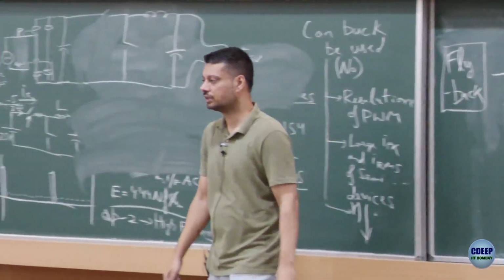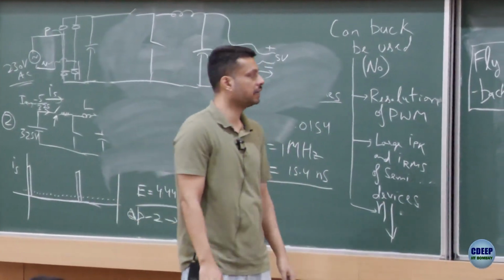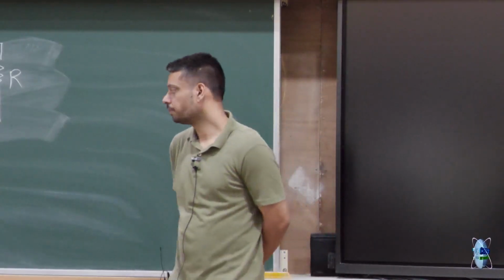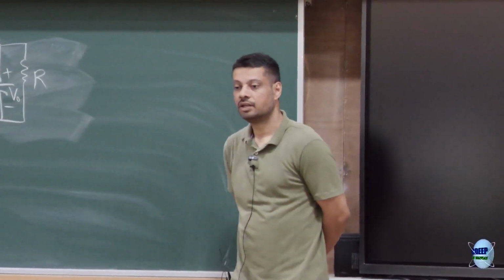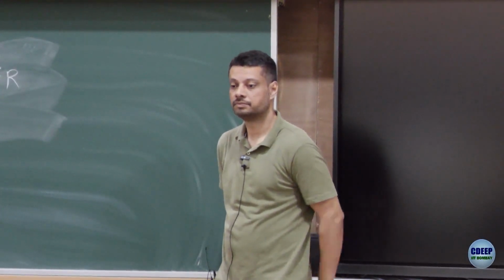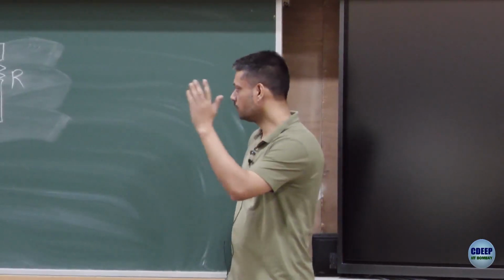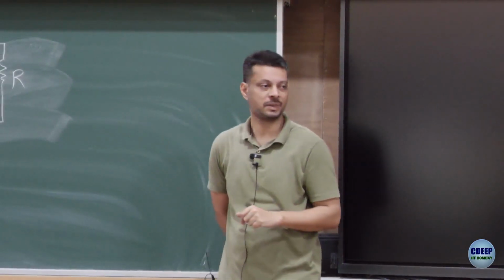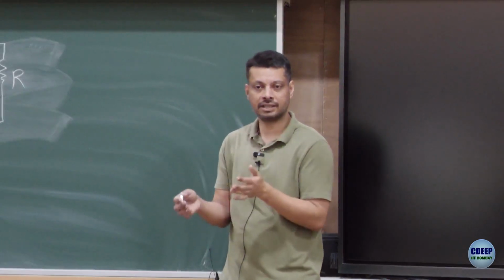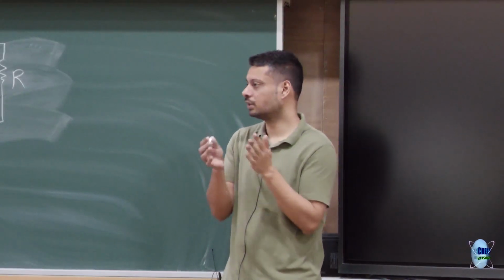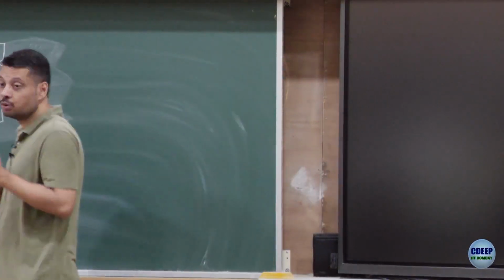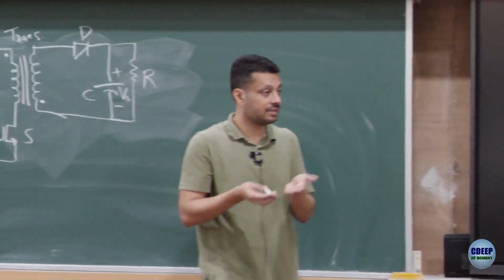Alright, first you can draw the circuit. I will explain how it operates. So, as someone suggested, if you want to do DC to DC, you can invert it at high frequency, pass it to a transformer, which will step it down, and then you rectify it. You can do it in a very literal way, just the way it is said.